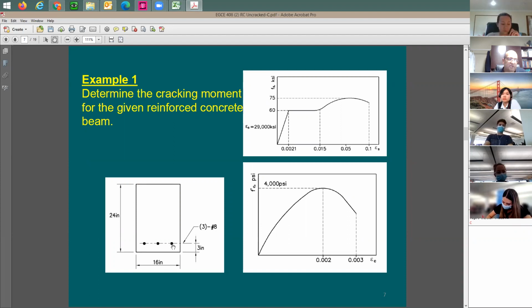Like the analysis is going to show you, maybe in this coming lecture, the amount of tension that you have in the rebars is going to be very similar to any tension that you're getting in the concrete in this region. So it doesn't really make any difference whether you put rebars or you don't put them before the cracking point.